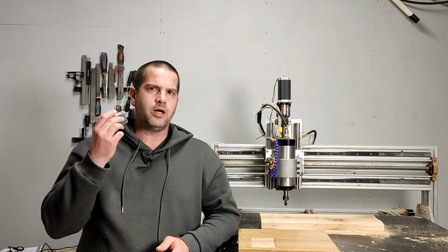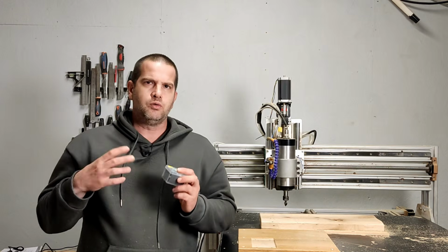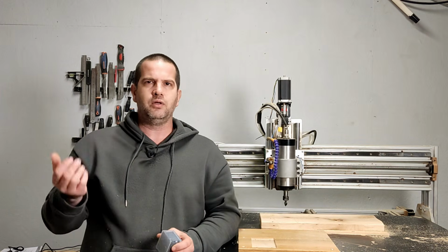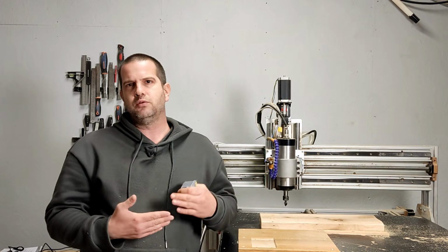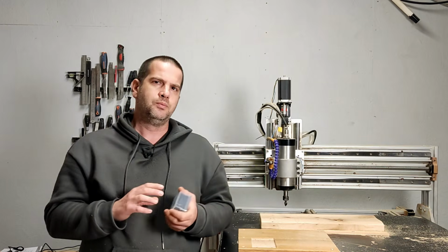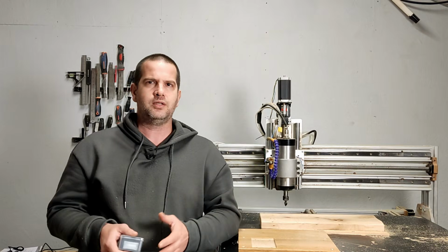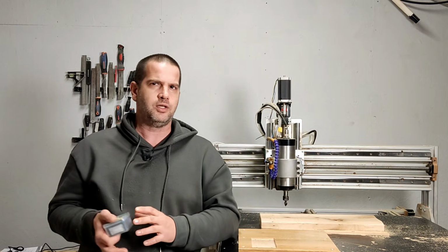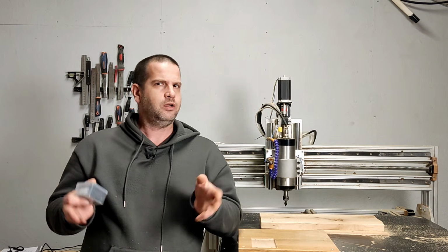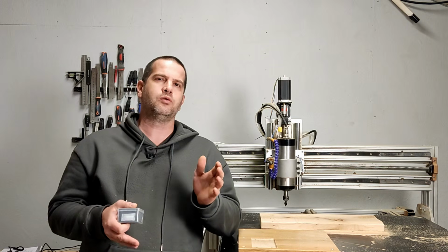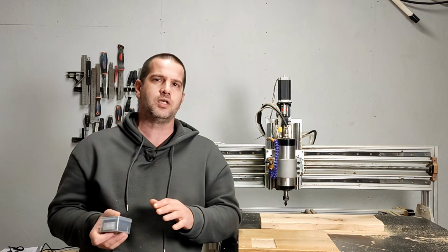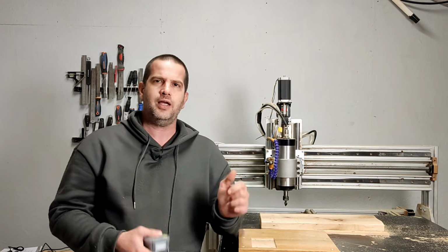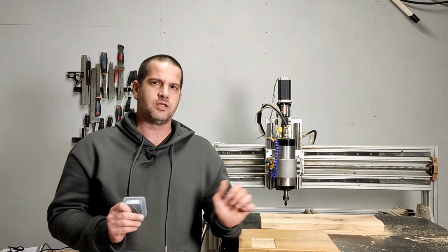In this video, we are going to use a 3D probe. I'm going to show you how to set things up in Universal Gcode Sender, where to set the origin, how to set the probing, how to adapt it in FreeCAD, and I will also show you a very useful macro that turns the surface into a 3D object. And for the ones that are not familiar with FreeCAD, I will show you how to use solely Universal Gcode Sender for probing the surface and adapting the toolpath to that surface.